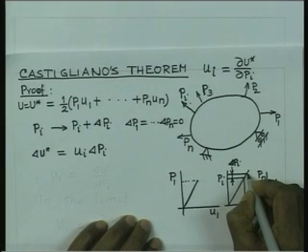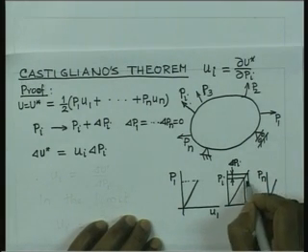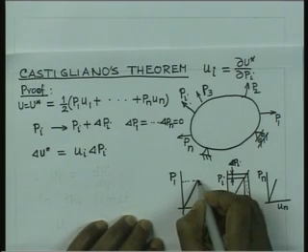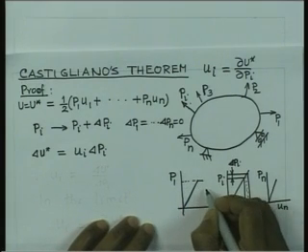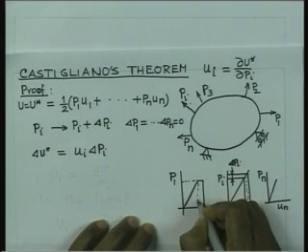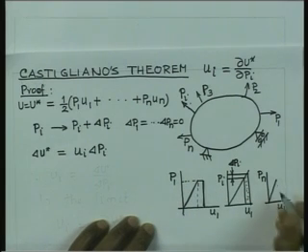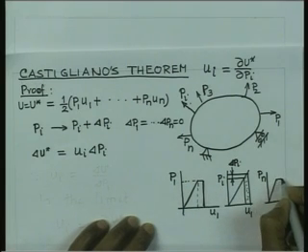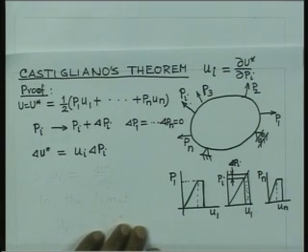This is going to cause some changes in the deflection here. The other loads are going to remain constant, but they will undergo some deflection. So, there will be some change in the deflection, and therefore some additional area under the load deflection curve. Similarly, this load would also have undergone some more deflection. So, there is going to be some work, which is represented by this area.